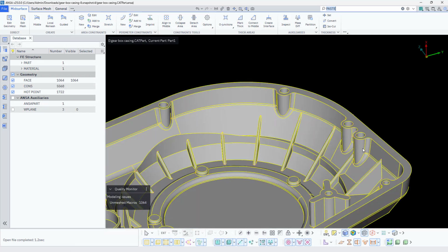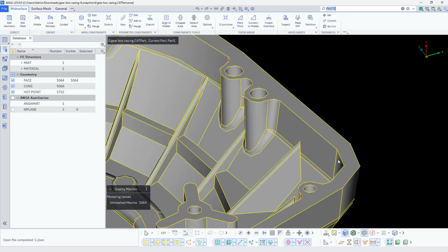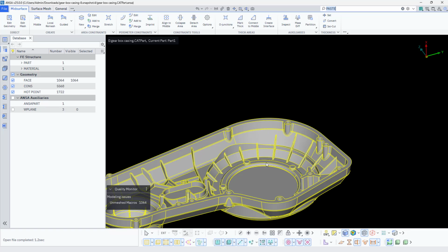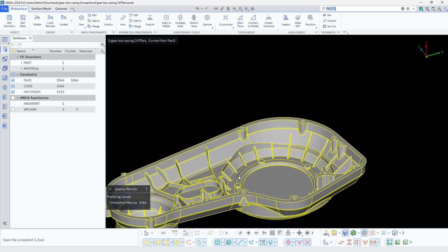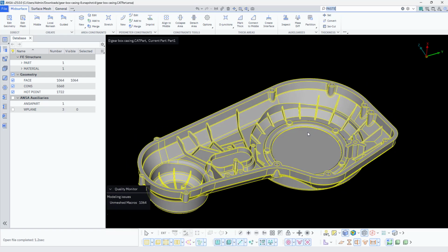If you want to see it again, press Ctrl+Z, and this is how it was before, and now Ctrl+Y, this is how it is. In short, it will add the number of nodes here, and then it will try to capture all the regions properly. And now, how do we start with meshing?